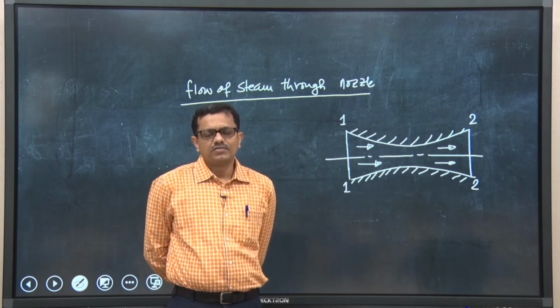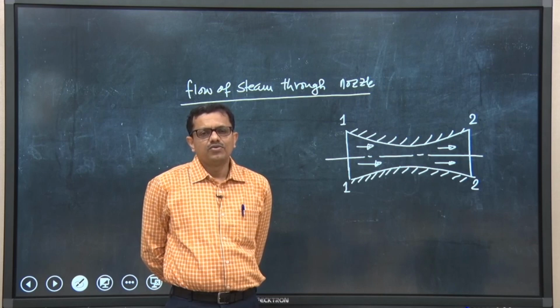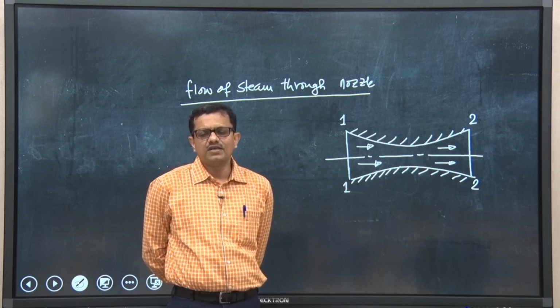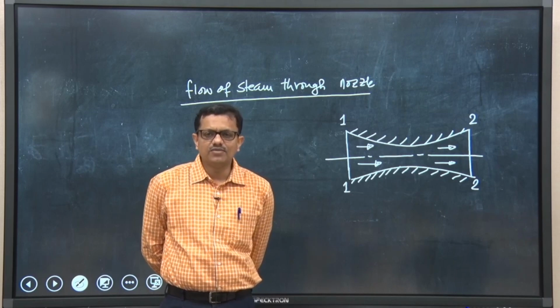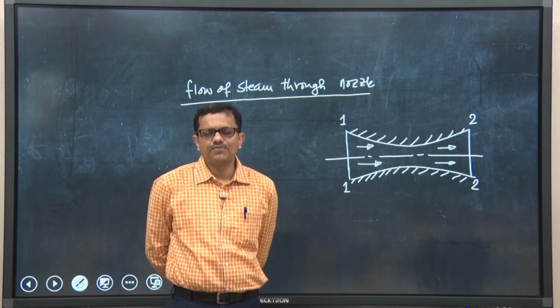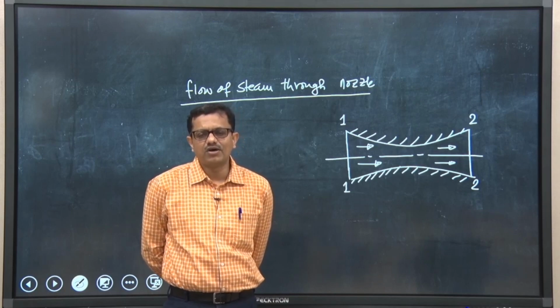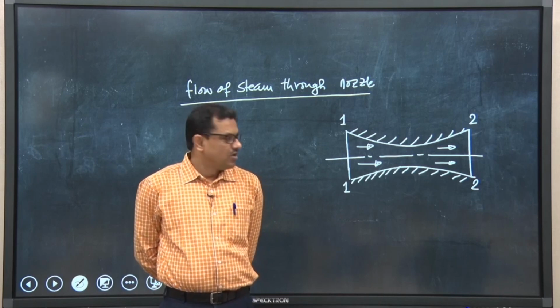that strikes the turbine blades, and when there is a deflection of the steam jets, there will be a change in momentum. In fact, there will be a loss of momentum and that momentum will be absorbed by the wheel of the turbine runner.